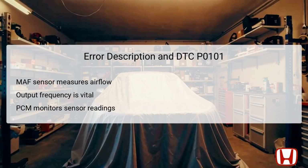DTC P0101 indicates a mass airflow (MAF) sensor circuit range performance problem, meaning that the output frequency of the MAF sensor is out of the expected range. The MAF sensor is essential for proper air metering, directly influencing engine performance and combustion efficiency. It specifically communicates the volume of air entering the engine to the powertrain control module, PCM, which adjusts the fuel injection accordingly.